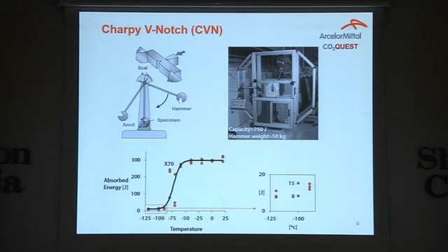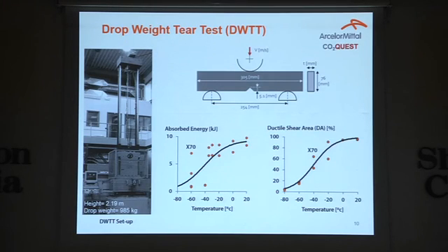So you see, for brittle fracture, we have quite low energy to break the material. Basically, the Charpy test is really well known. It's an old school test that they use in the labs to break the material. It's just a transformation of, let's say, potential energy to kinetic energy, and we observe how much energy can be absorbed by our material. We also have some scatter at low temperatures, which varies sometimes between 5 to 15 joules. Another way to deal with this material selection is a more realistic test, which is a drop weight tear test.